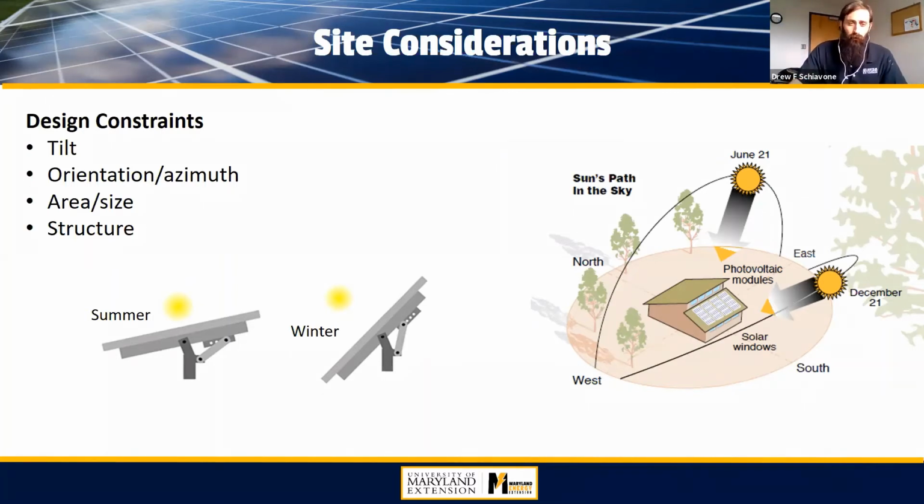So there are some restrictions with a rooftop system. Obviously, I mentioned the slope of the roof is one area, but if your house or a barn or whatever you're installing on the roof of is not oriented south, you're kind of restricted there. You definitely don't want to put it on the north side. If it's slightly to the east or west, that may be all right as well. But this is an area that we've touched on in previous weeks, looking at PVWatts software put out there by NREL.